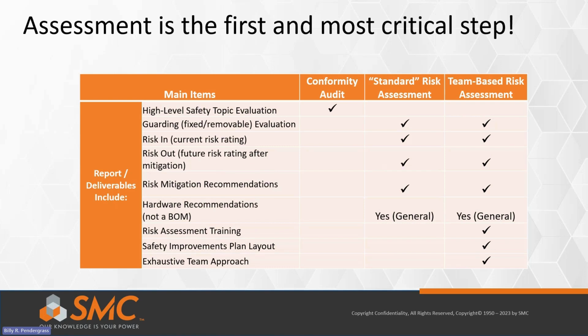A multiple machine, plant-wide audit provides a high level analysis of specific safety areas, analyzes guarding and components that perform safety functions, and identifies and labels e-stops and safety devices and/or isolation devices. Risk assessments offered by the SMC team, safety engineer or consultant, have limited customer involvement, typically just operations and maintenance.